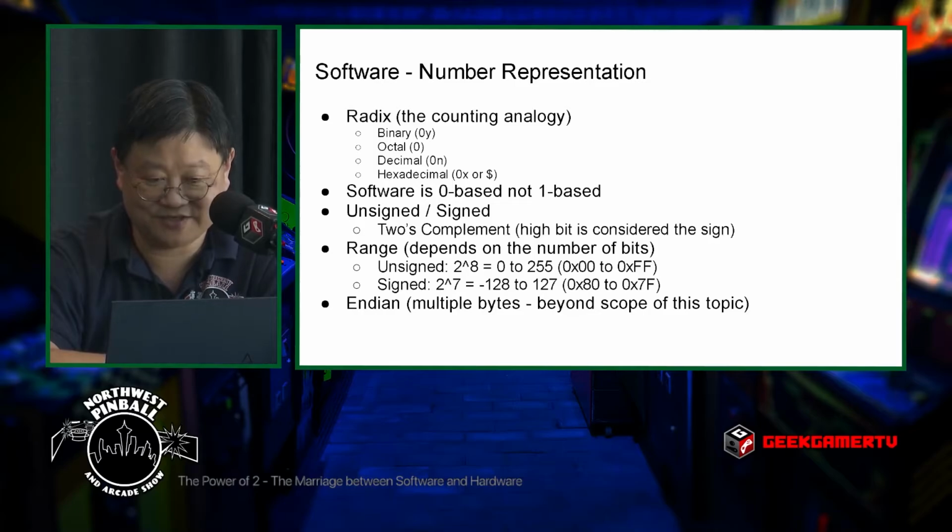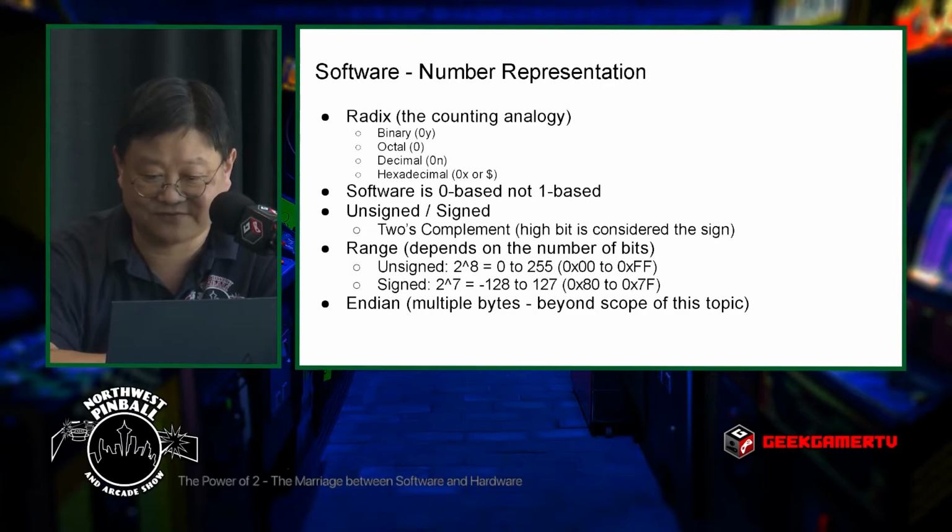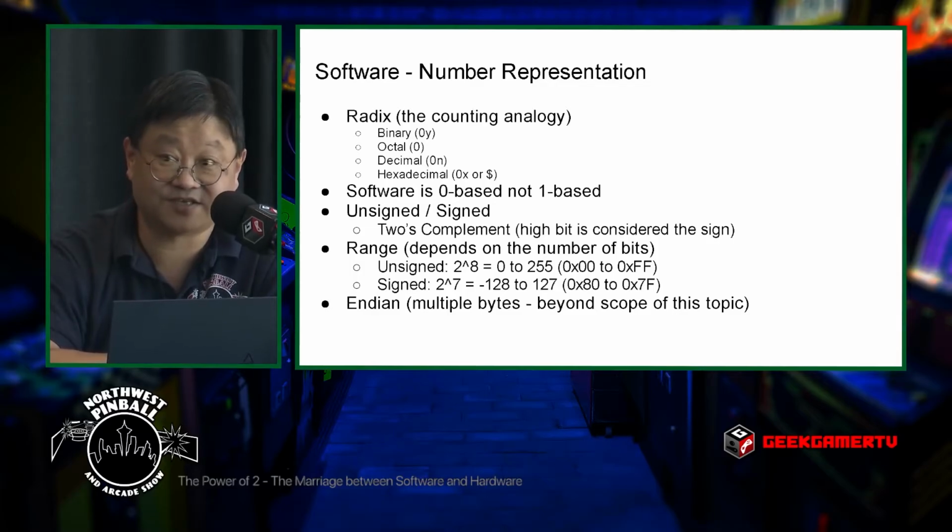Number representation, typically, and we'll keep it simple here for 8-bit numbers, but numbers can either be signed or unsigned, and a processor will treat a comparison differently depending on whether you're using signed or unsigned. I just mentioned there 2's complement, again, if you're familiar with these number representation schemes. The signed bit takes away one of the available bits.